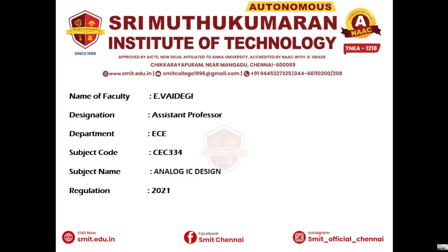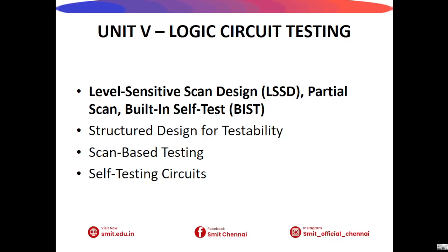Today the video lecture is from the subject CEC 334 Analog IC Design. In this video lecture we see the topics from Unit 5 of Analog IC Design. Today we will study three important structured design for testability techniques: level sensitive scan design, partial scan design, and built-in self-test. These techniques are widely used in modern VLSI circuits to improve testing efficiency and fault detection. They help engineers verify complex integrated circuits quickly and accurately.